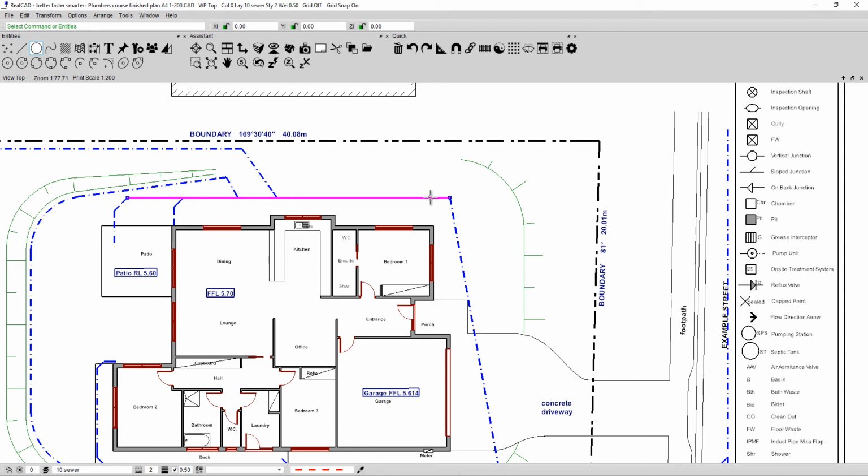For this line, hold down the Shift or Control key to select two lines. Now they're joined at this corner. Then I'm going to use the Transform tool and Offset. So this is where I can offset a series of lines or a single line by wherever I click, basically. And it wants to know, do I want round corners? And I say no, just leave that unticked, choose OK.